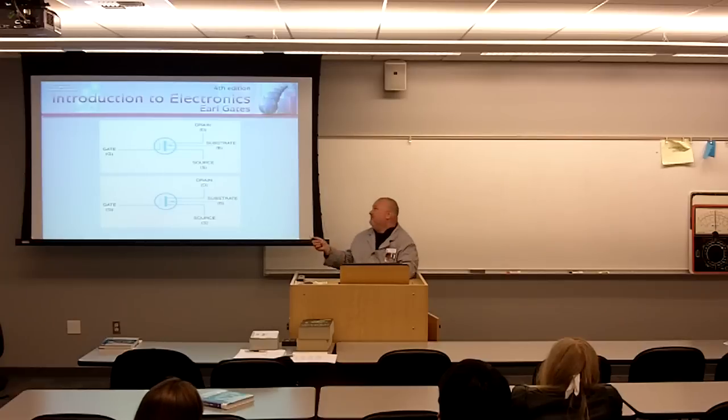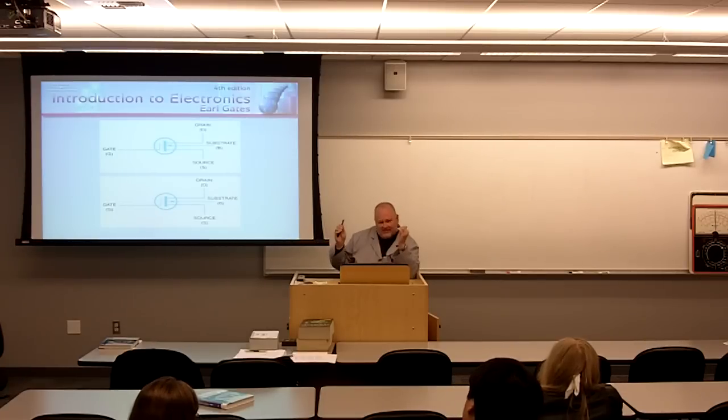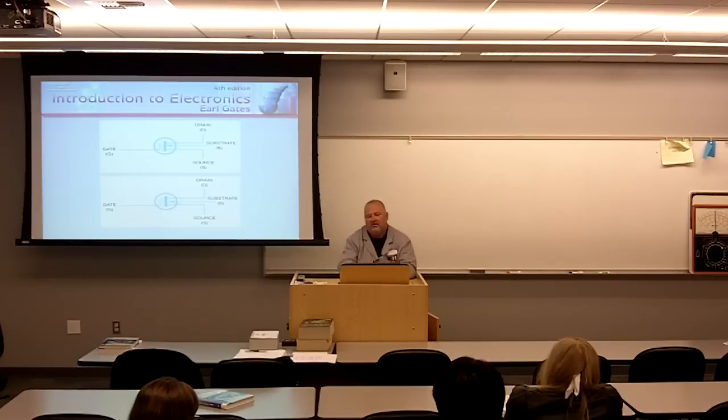The reason that we have this additional lead, this substrate lead, is that because these devices are so efficient and they operate at such low voltages, in some cases you want to link all those substrates together to make sure they're at the same electrical potential. So engineers will determine how those are all going to be tied together, because any difference in potential that you build up will be a voltage that can start to develop an electrostatic field, and all of a sudden you're going to have this thing doing something you don't want it to do.